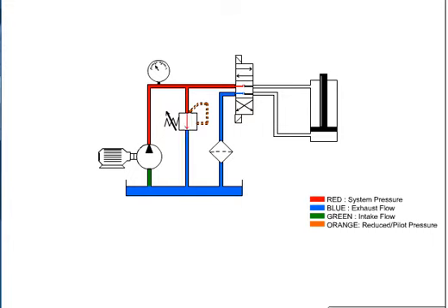If flow were to be blocked in neutral or when the directional control valve is centered, it would force flow over the relief valve. This could possibly create an excessive amount of heat and would be an incorrect design. A closed center circuit blocks pump flow at the directional control valve, in neutral or when centered. We must utilize a pressure-compensated pump such as a piston pump, which will de-stroke.